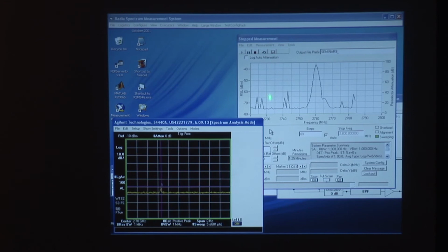The reason we know that they're not the radar emission is I was actually able to watch the spectrum analyzer screen on each of these data points as it was developing the spectrum, and I saw that the emissions here looked like momentary pulses. They could either have been noise spikes or they could have been really distant radars. They were not this radar. And I could tell because I could see what was happening in the time domain as these points were taken.